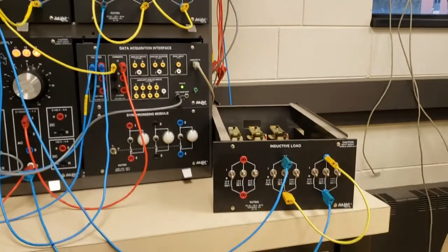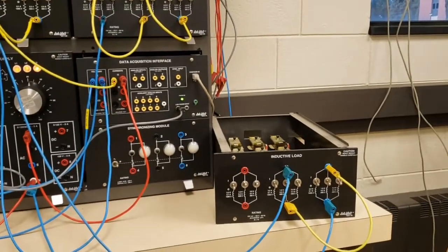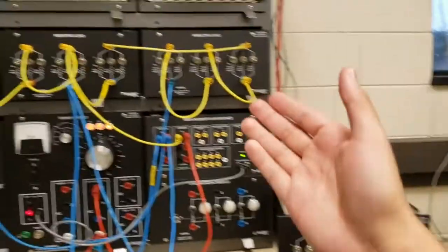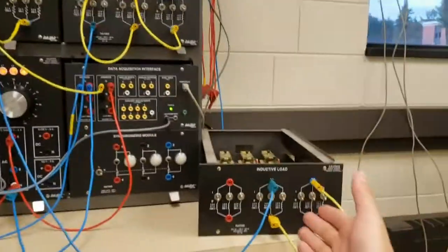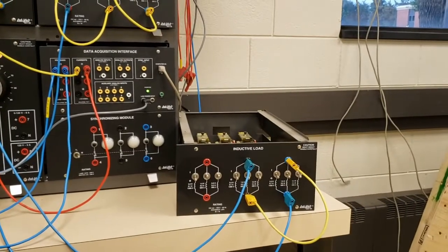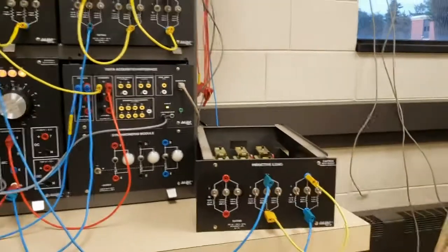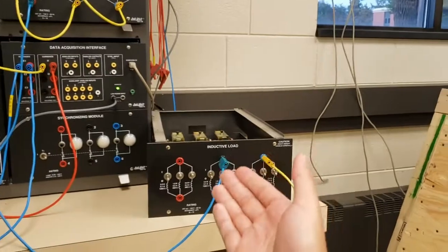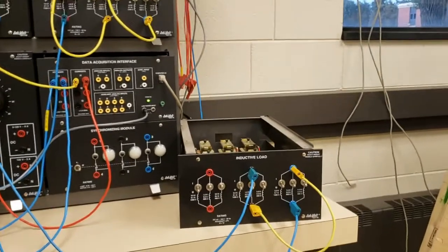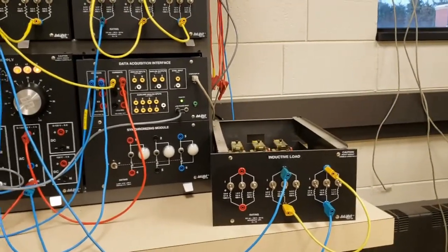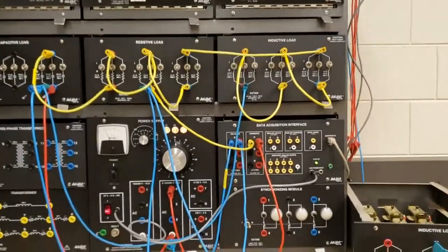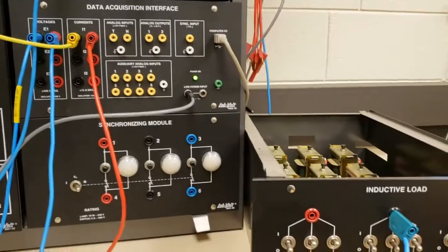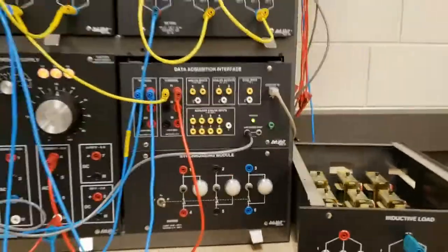Now, I should have had some more hindsight to remember that the actual load is not available because all the terminals are used up. But anyways, I just took one of the modules out and connected it up, and so I have a corrective load. You can see it's inductive, which kind of makes sense because the load is net capacitive, so you need an inductive load to correct its power factor. And I set it up, and I've done everything.